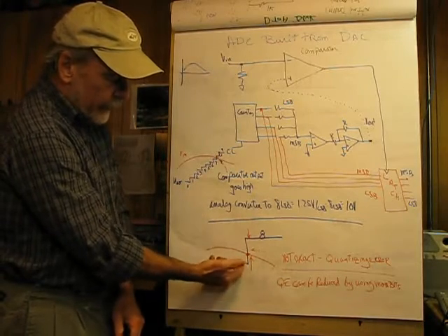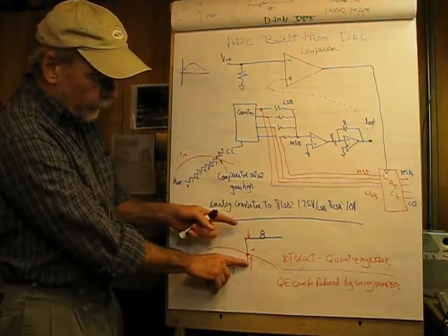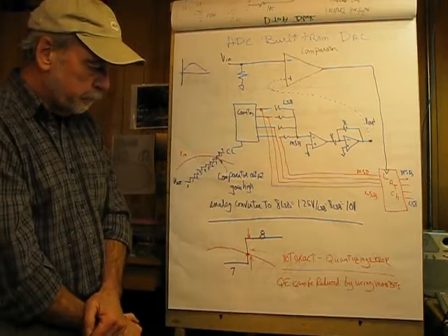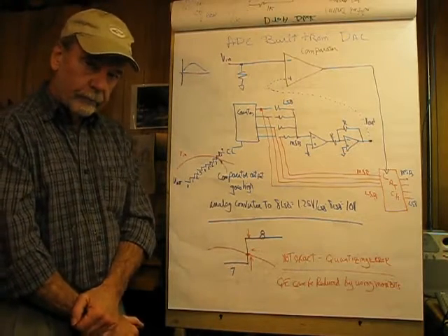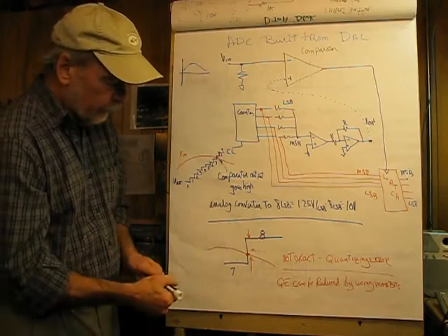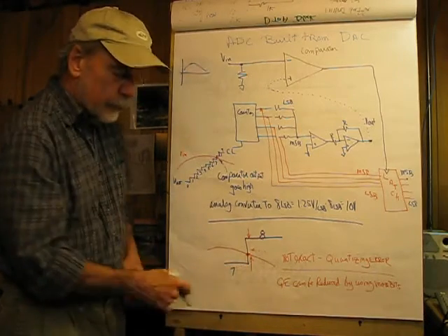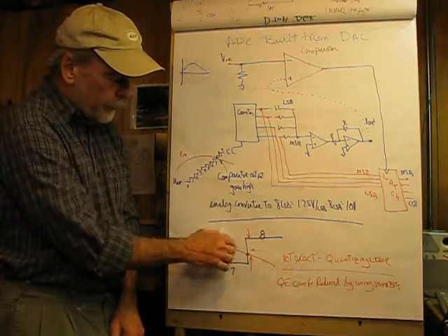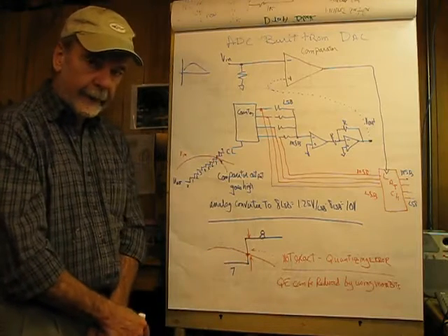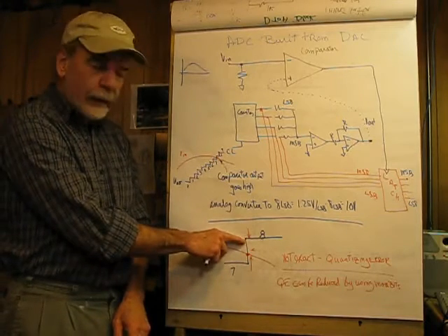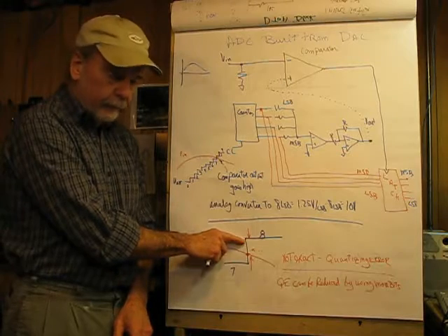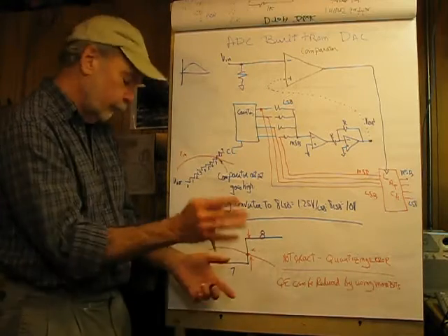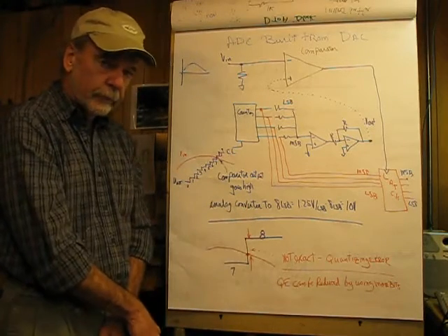And what we see is that effect down here. I've tried to recreate that between 7 and 8, and this difference here would be the quantizing error, and the QE can have a range of 0. That is, if the input voltage were right here, and it called that a 7, binary 7 would be 0 error, up to 0.9999 LSB. If it were really, really close to 8, but not quite, it would call it 7, because it hasn't crossed 8.